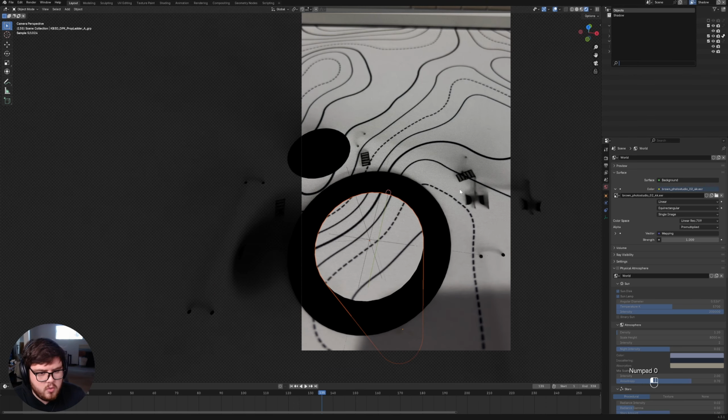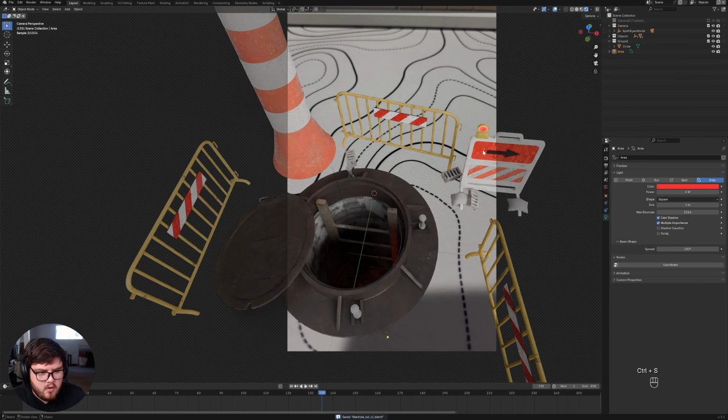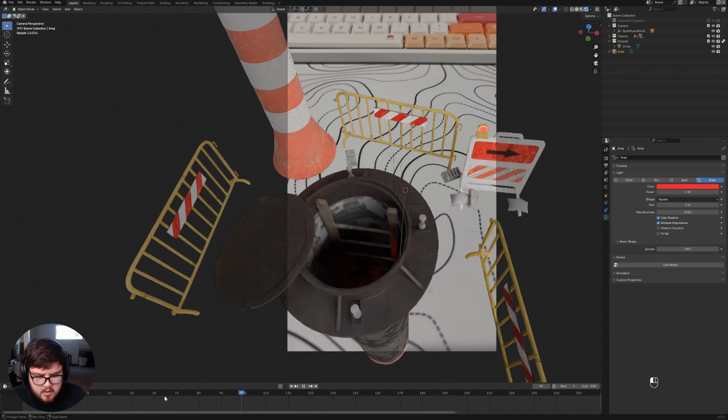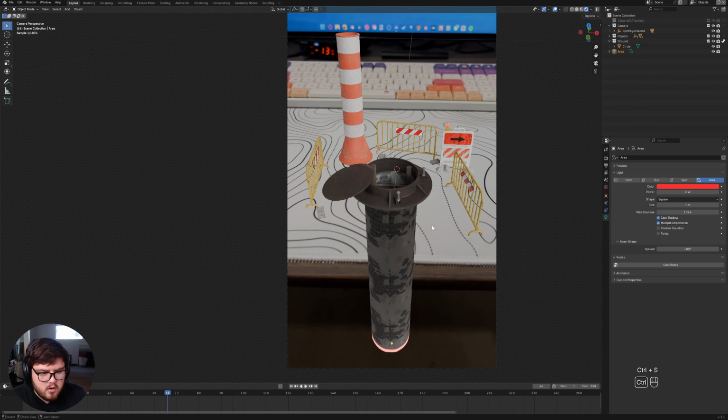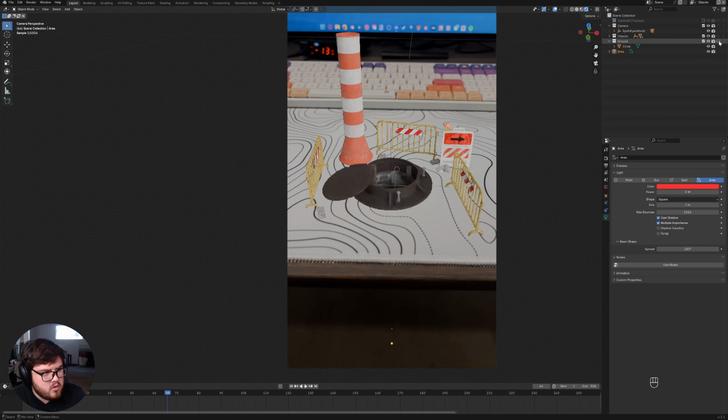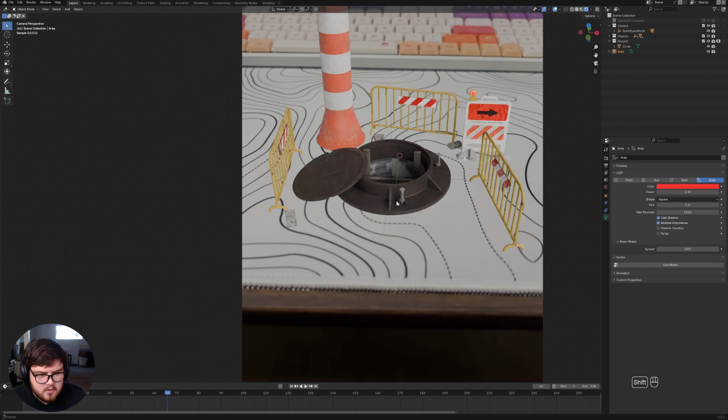And then we'll go over to objects right here, and all that is loading in. And if we turn this to indirect only, you can see we're not having the shadow into the scene, but it's still kind of indirectly affecting, but we do still see the bottom of the hole here. So what we actually might try to do is come and select holdout up here. And so instead of indirect only, we'll select holdout. And then there we go. That is doing exactly what we want.